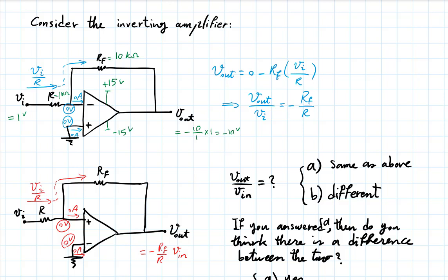Right now it's 0 volts at the negative input. Assume that there is a little bit of noise, and momentarily some signal induced there raises it to 10 millivolts. So momentarily, the negative side becomes more positive than the positive side, right? You have 10 millivolts.